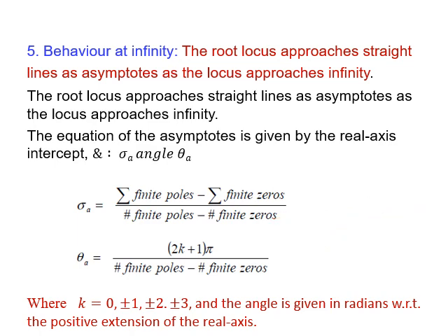Let us redraw them. So this is the S-plane. We have 1, 2, and 3. We agreed that there is root locus here and root locus here. So I need to know for these poles what direction they are going to go toward infinity. Direction means angle. So I need to take these 2 with a certain angle toward infinity. What is that angle? We will calculate the angle. The angle is to be calculated from this equation. I will explain it after a while.